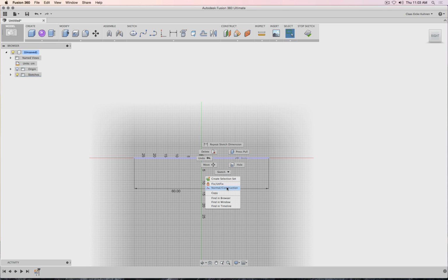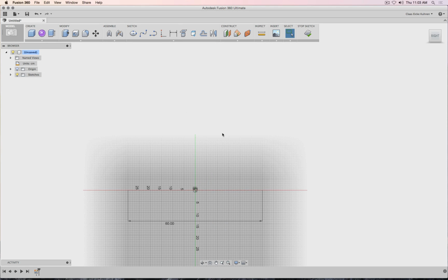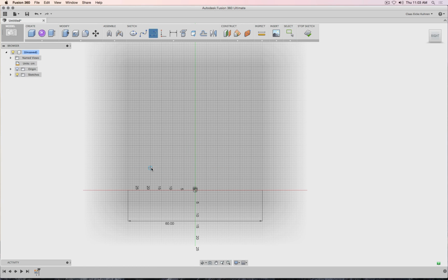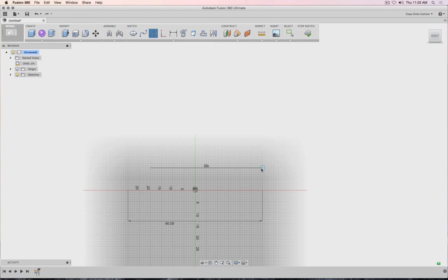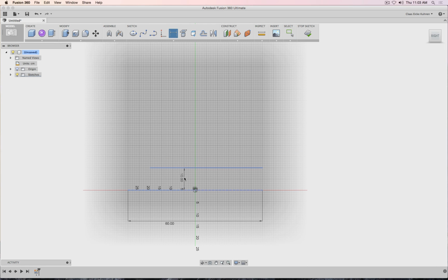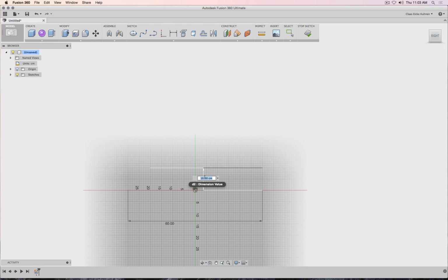So I'm going to dimension this one since I'm drawing there already. My height is 48 centimeters, and this piece up there should be roughly 50 centimeters. That's kind of like maybe the width of the seat shell. And I want those two to be 48 centimeters apart. So I select both lines and plug in a dimension 48 there. Perfect.